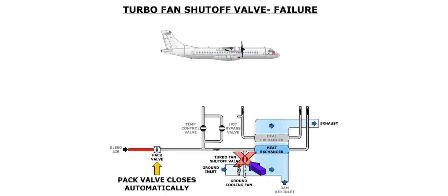If the turbofan shutoff valve is not in the commanded position, the associated pack valve will automatically close to protect the pack against any damage.